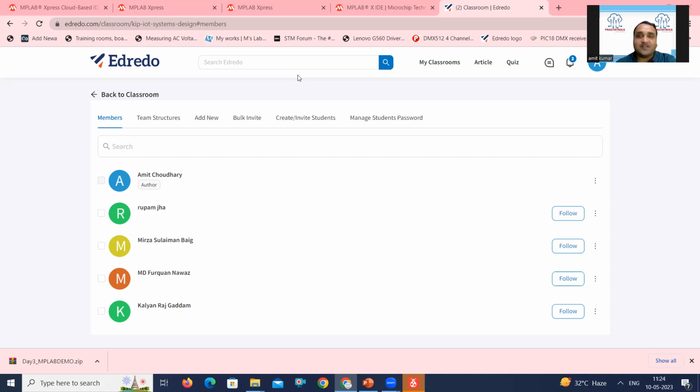So we will be learning that here. But if we are using the PIC microcontroller, you don't have to attach those current drivers, resistors and semiconductors separately. In one microcontroller, you have all the features. You will just have to attach the GSM and the buzzer, write the program, and it can start functioning. Now the program, whatever you write, you will write in the MPLAB IDE. Okay, sir.